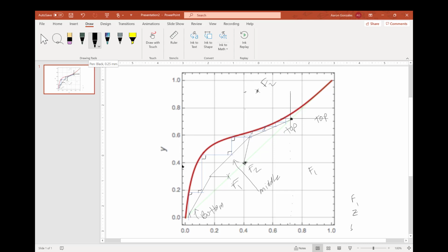So coming to the bottom, it would be 1. However, it's not 1 because in the problem statement, it said that it is a partial reboiler, so the partial reboiler is your first stage. Then, walking up, we have 1, 2, 3, 4, 5. Now here's where it gets tricky. It doesn't meet right there for the 6th one. You are crossing your distillate composition, your 0.72 line, before you get to the equilibrium line. So it's actually, the way I have it drawn, about 3/4 of a tray. The way the book has it, it has it as 5.5, but hey, we're close enough. So what you have here is that you're going to need 5.75 equilibrium stages plus a partial reboiler.